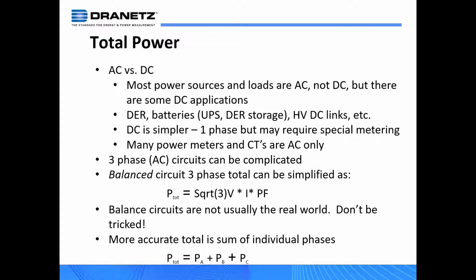The takeaway is that we need to monitor each phase and line individually, and the metering will handle adding that up properly to give you the total power in the system. So you need to monitor phases A, B, and C in a 3-phase system individually. Most capable tools are 3-phase tools, which you should be using, and they will do all this for you to give you accurate numbers. Do not take one phase and add them up or multiply them and make those assumptions.